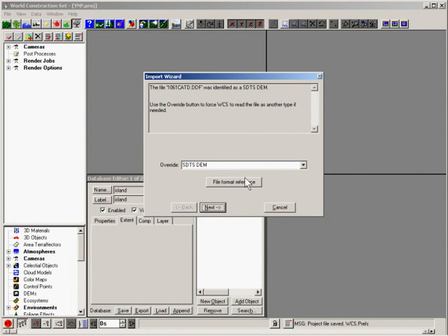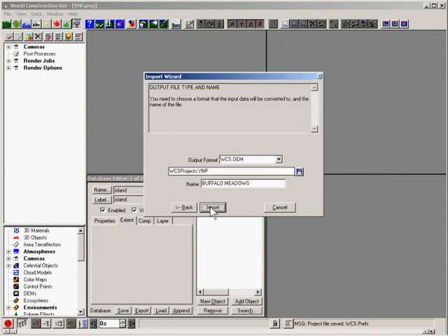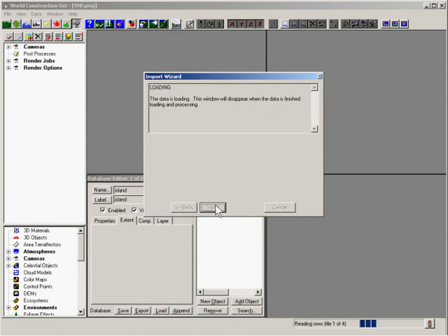This will launch the now familiar import wizard, which will correctly identify the files as SDTS DEMs. Click Next to the Load As window, accept the defaults, and continue to Output File Type and Name. Change the name to YNP-10M for 10 meters and import.